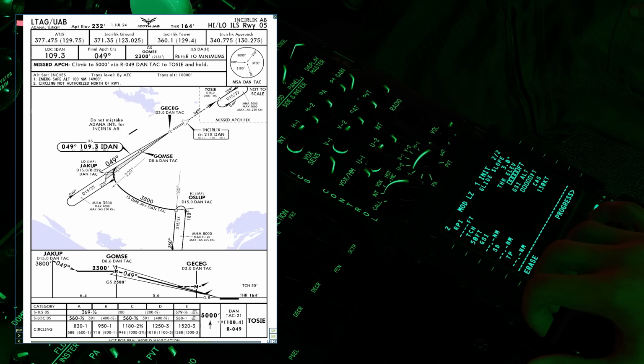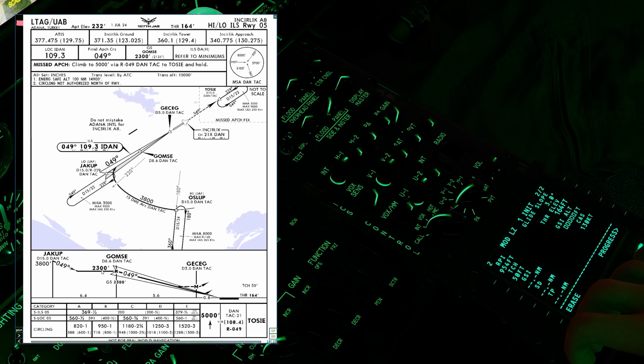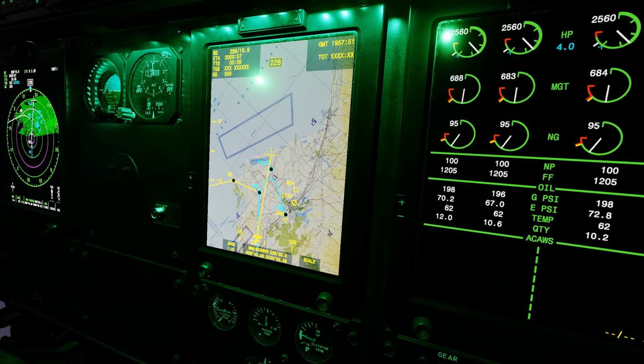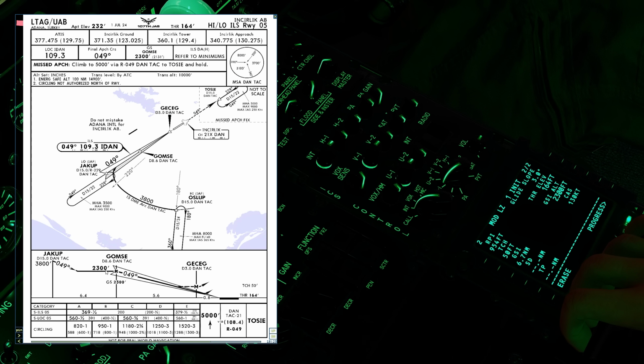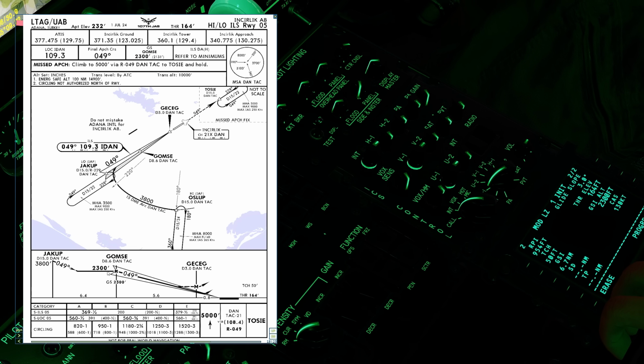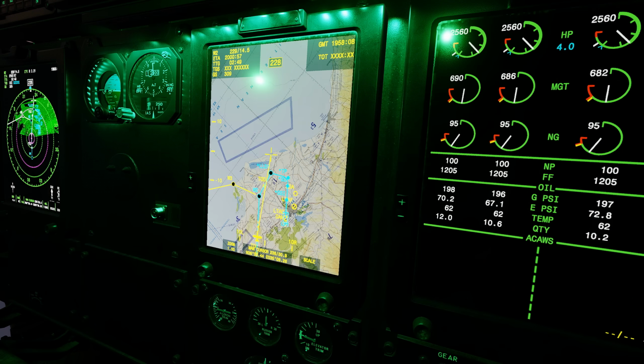Okay, threshold elevation, same as the touchdown zone, correct? Yep, 164. 164. And glide slope intercept altitude? Looks like 2,300. 2300 on the GSI. Alright, I just need 2 points, a slowdown point and a turning point. Slow down, let's make that 12. And let's make the turning point 15, please. 15 for the turning point approach fix.